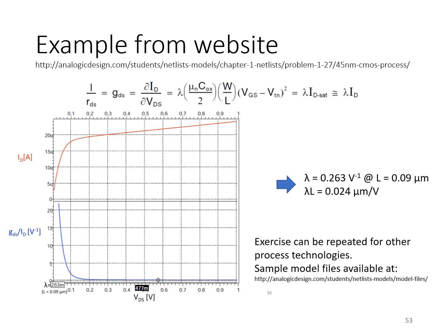Here are plots where VGS is being held constant and VDS is being swept, and you see here in active mode a fairly straight line, which can be used to find RDS and hence lambda of this transistor. Again, remember that lambda depends strongly on L, so the value of lambda will be different when you rerun the test bench for different values of gate length.